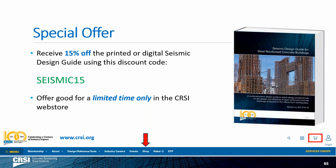That's a very good question. And we do have an example for a low-rise building where we've got the Swiss cheese of openings in it. What you need to be careful in those cases is, is it actually a wall section, or is it a pier, based on the overall dimensions of the section that you're looking at.